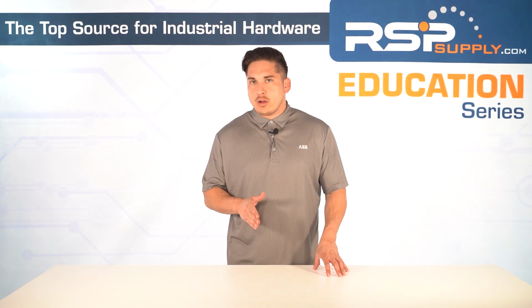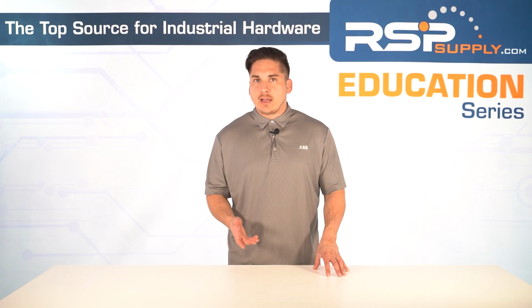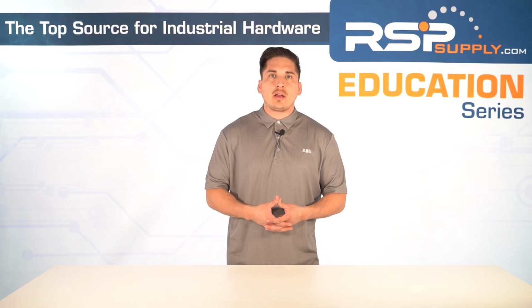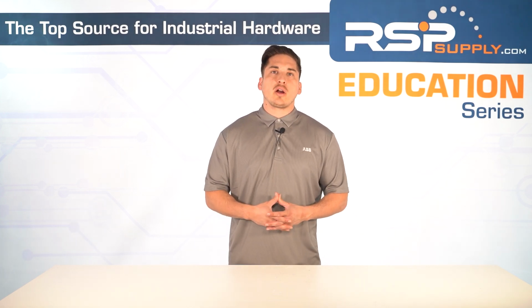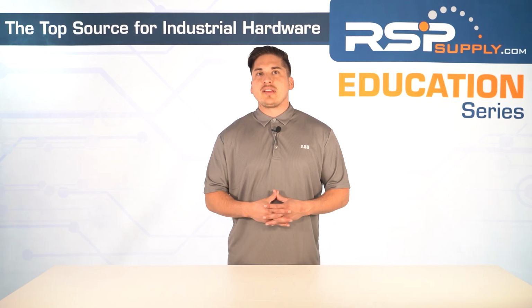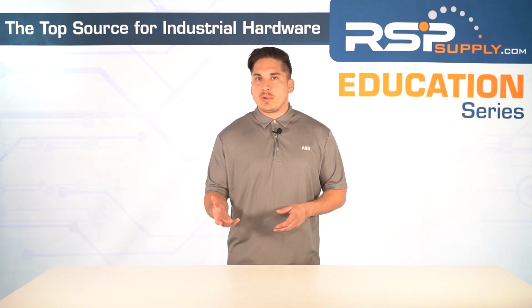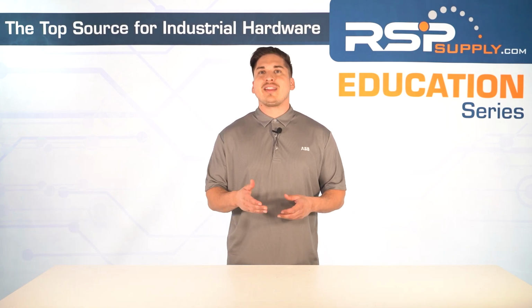Imagine you're out in the field. A pump isn't performing right and the control room's getting incorrect readings. You're staring at a screen wondering, is it the sensor or the wiring or the signal itself? This is where understanding how signals work, 4 to 20 milliamp, 0 to 10 volt, Fieldbus and HART, for example, makes all the difference. These aren't just technical terms. They're the language that your instruments use to talk to your PLCs, your distributed control system, and ultimately to you.